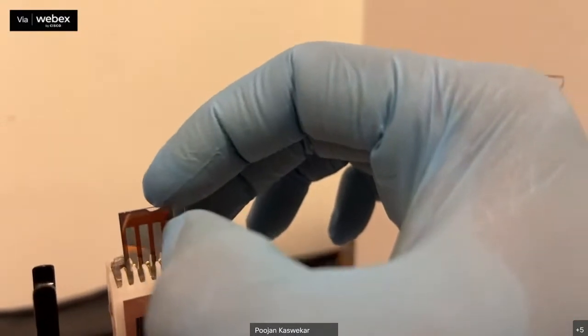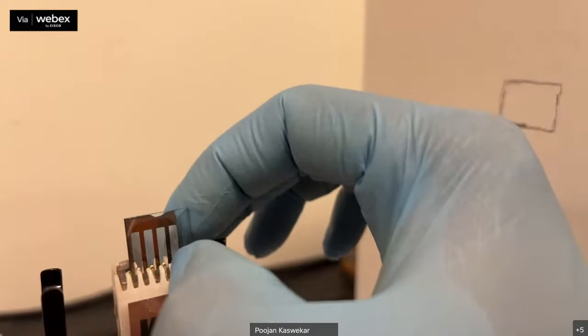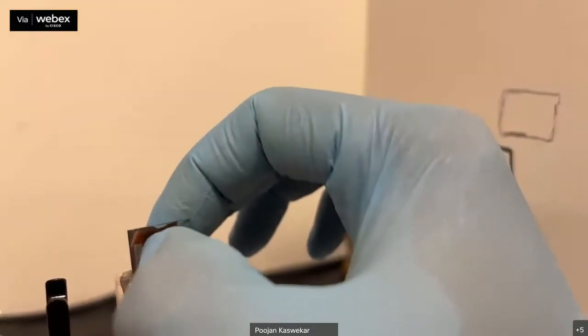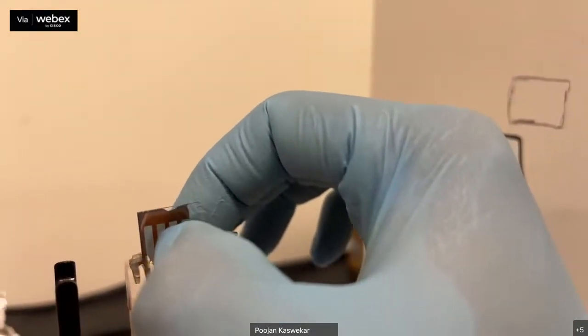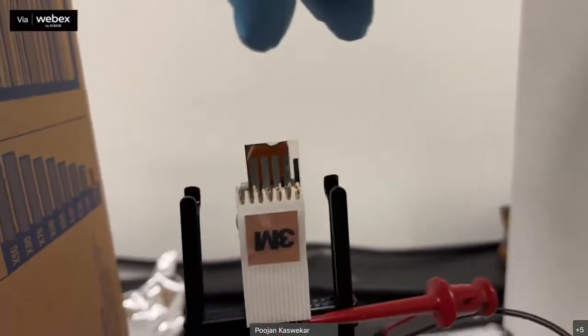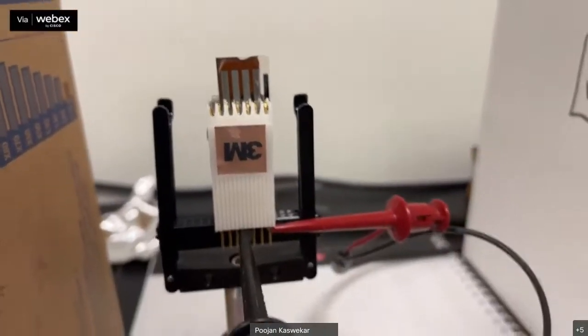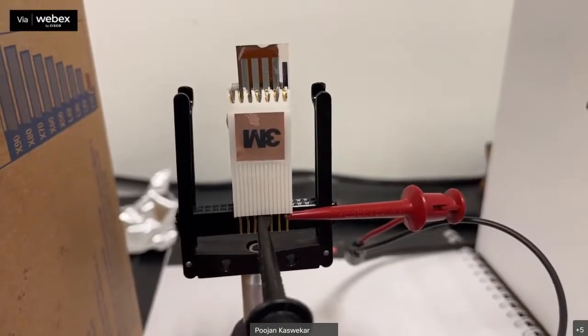Whatever charge is generated over that finger area goes to the finger over there. So we will only consider this area before the recombination. Otherwise, from other places, whatever is coming, most of it will be recombining. So the cell area we consider is the typical area where we contact the solar cell. So you are taking only the silver area. Yes. So the in-between area you are not considering. No, we are not considering the in-between area.